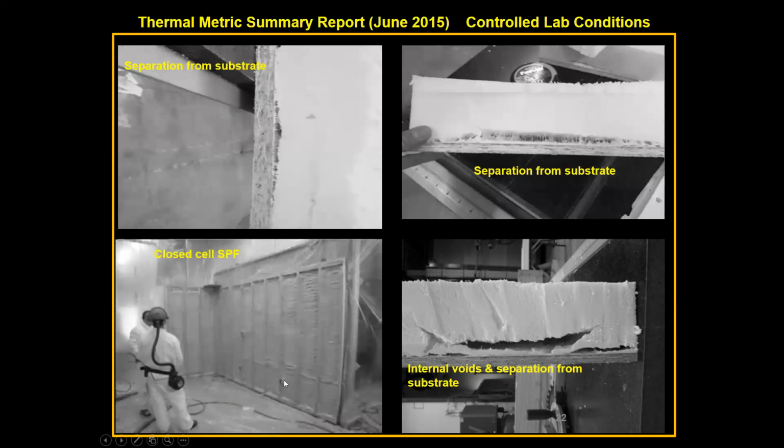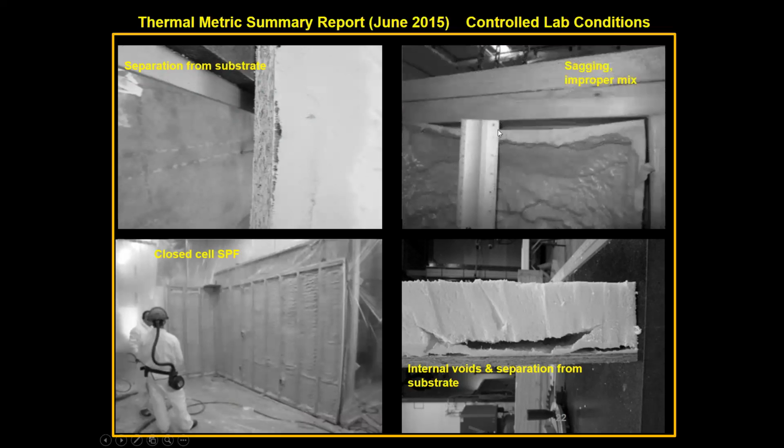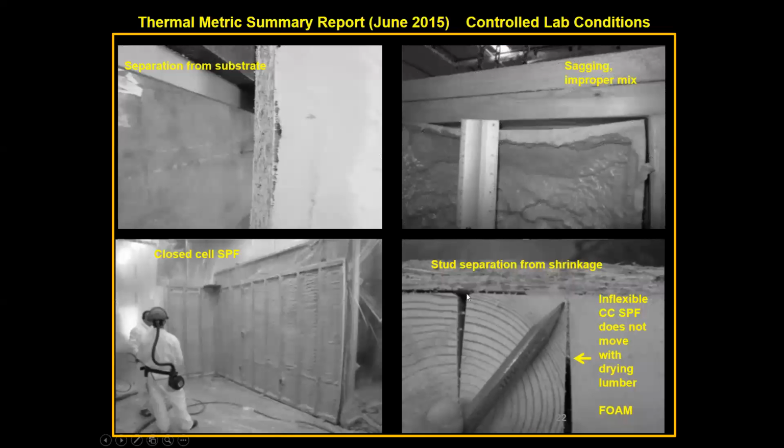Again, here's the closed cell foam, just so you can see the difference. But here, this is what happens when you have poor mixes. That's not correct. And these are left this way. This is the way I found these ready for cover. This is, again, internal void, more separation. And this is what happens when lumber moves with closed cell. Again, this is the gap that's left.